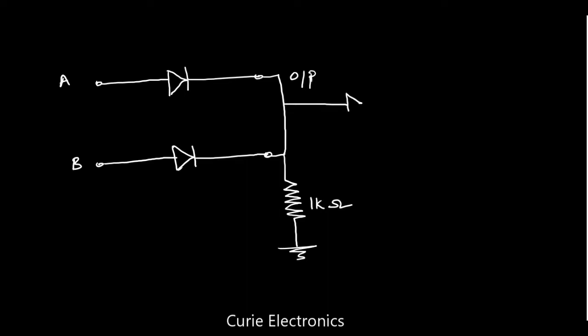One LED I am connecting. There also we use a current limiting resistor which will go to the ground. Here I am using a 100 ohm resistor, and this is the light emitting diode, that's an LED. Now this should work as an OR gate.